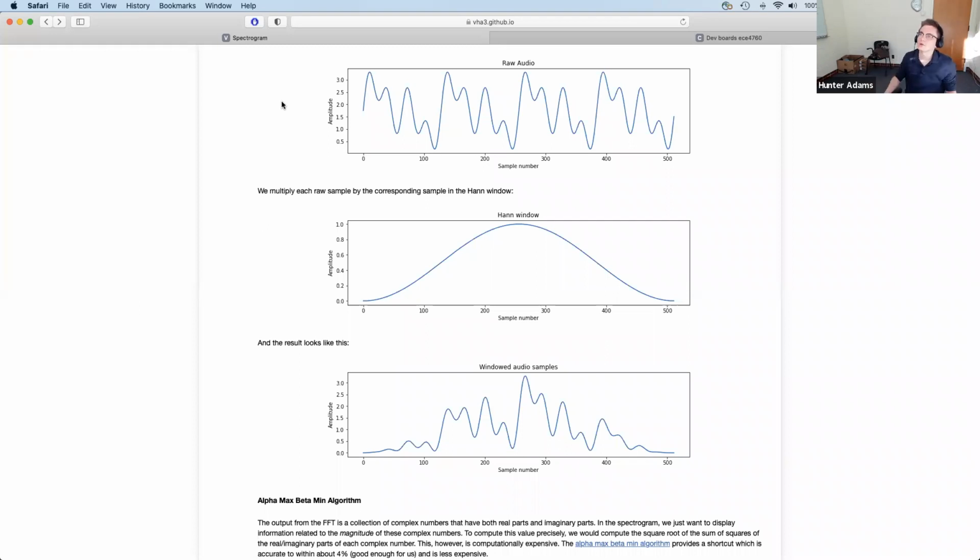For reasons that were very similar to when in lab 1 you did not linearly envelope your bird calls, you heard a bunch of high frequency stuff at the output, clicks and pops and such, right? That sort of thing will manifest in the FFT output as well. So by windowing this, we get rid of all of that high frequency noise. It's not signal, it's just noise.